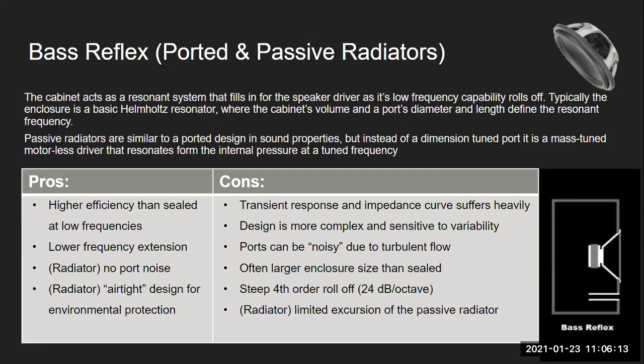Not to us engineers, we're like, yes, this is a basic equation, Helmholtz. Yes, it's pretty easy for the DIY person as well. However, it's more finicky with regard to the dimensions of the port length, port size, and the volume. You have to be more precise with your calculations. You can't be adding in braces after the fact and just taking away volume. It will change your tuning frequency, which will change your overall frequency response. So it's a little more sensitive in that way.